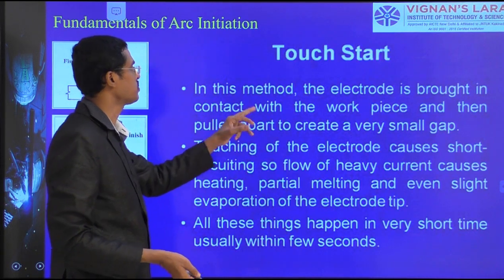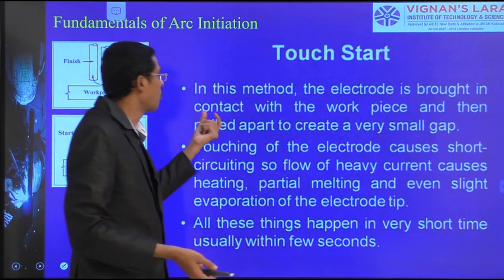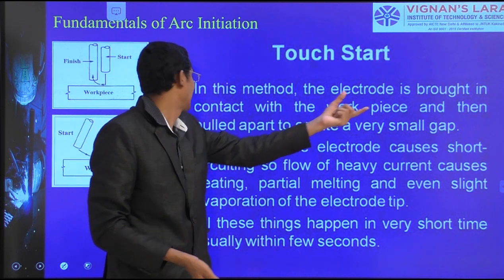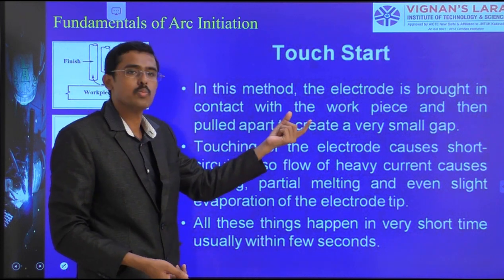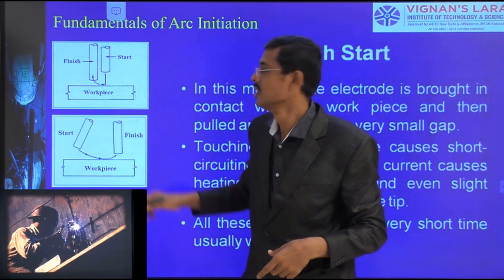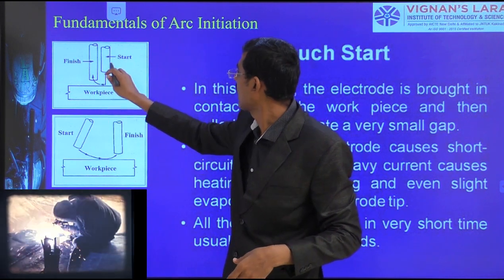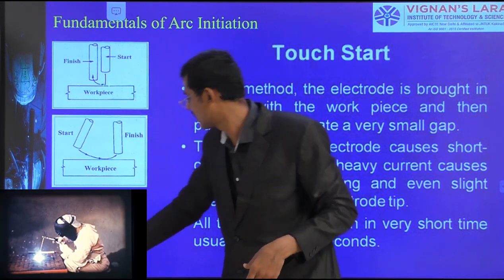Touch start method. In this method, the electrode is brought in contact with the workpiece and then pulled apart to create a very small gap. What I am doing, the workpiece is there and I am coming down, I am having a touch here.